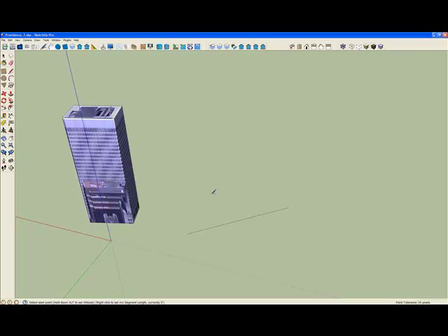I create another arc. There's also inferencing of edges to arcs. So for example, if I create a line, it'll tell me that it's tangent to the existing arc. Or I can start at this end and it'll tell me that I'm on the arc endpoint, and then it'll tell me that I'm tangent to the arc, and it'll tell me if I'm at the vertex of the other end.